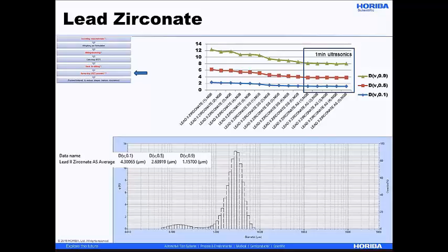In this case, we do not want to pack because this fine peak on the finer side, around about 200 nanometer, can cause some serious problem when we want to pack into a specific shape. So the general rule of thumb for packing is that you want it to be unimodal with the narrow distribution. So anytime you see bimodal distribution, you might want to avoid that.